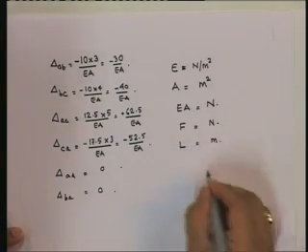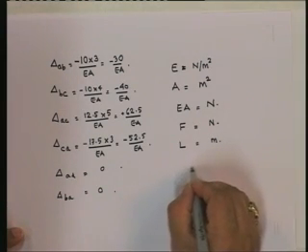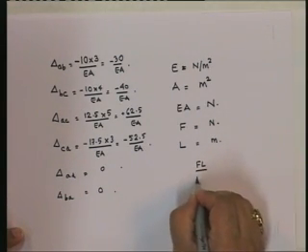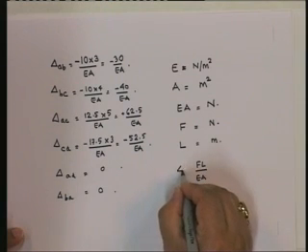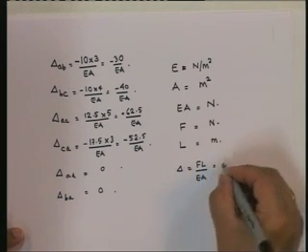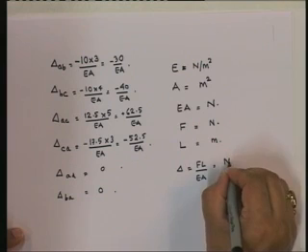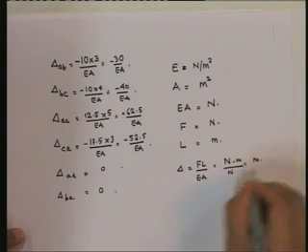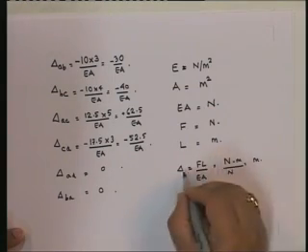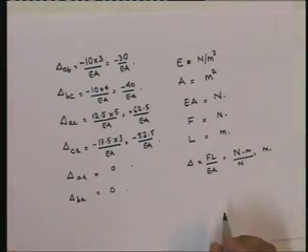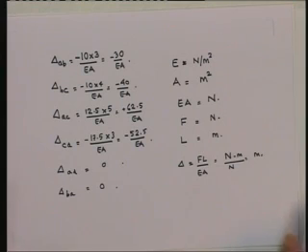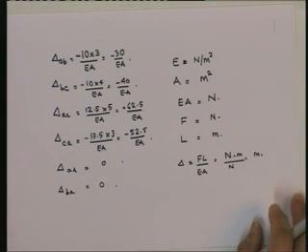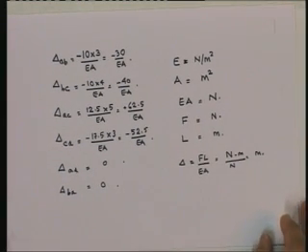Length is meter. So now when I write down delta is equal to FL upon EA, let's see what I am doing actually. Newton meter upon Newton. Units consistent. Delta, which is the displacement or deformation, has to be in meters. Okay? So we have dimensional consistency, and that is very important to know when you actually solve a problem.